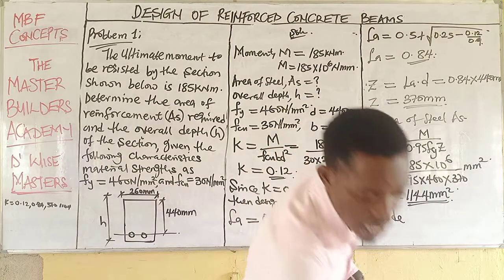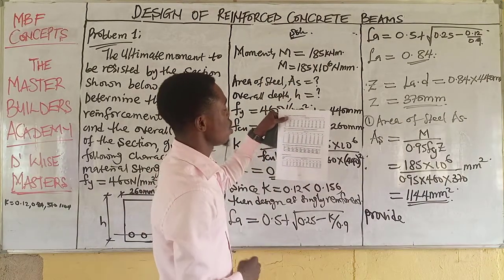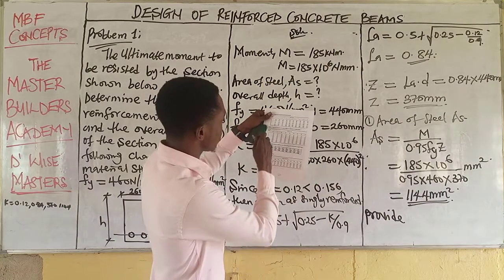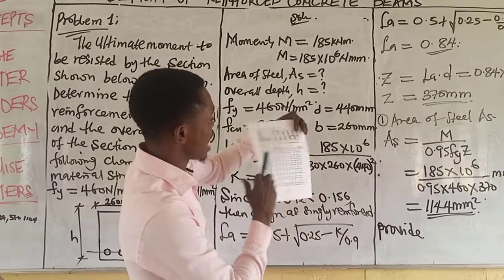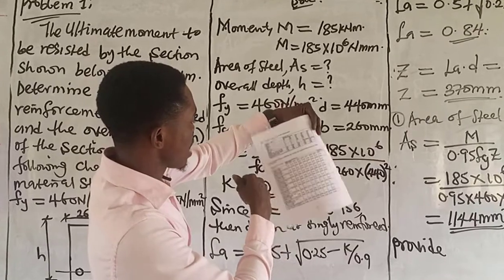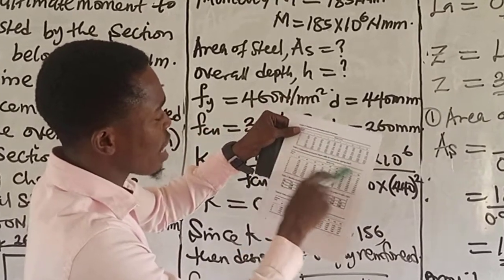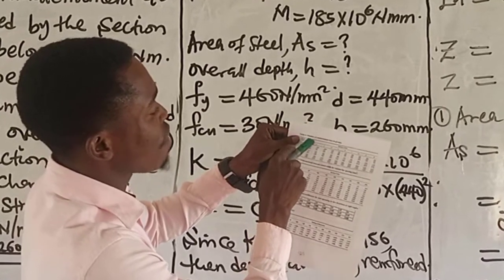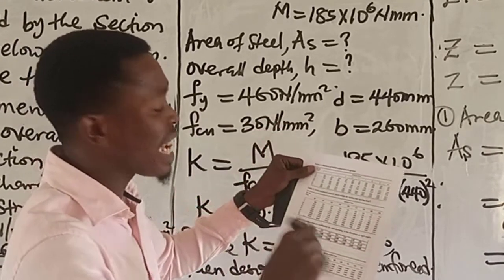So now, if this is my table, and this is the beam section, all I need to do is to trace. I have different types of beam design table here. So before you pick any of the options, ensure that you read the headings very well. The first table I have there now is table 3, which is number of reinforced bars in groups.